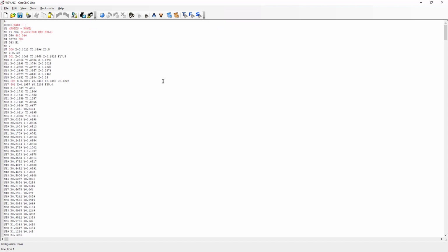You can see now that the NC code's been generated and taken inside the text editor. Within the text editor, you can do lots of powerful things like you can renumber, you can do a search, copy, replace. There's calculators provided if you want to perform calculations. And you also have the ability to upload and download the CNC programs to and from your CNC machines using the included RS-232 software. And of course, you can save, print, and all those options as well.